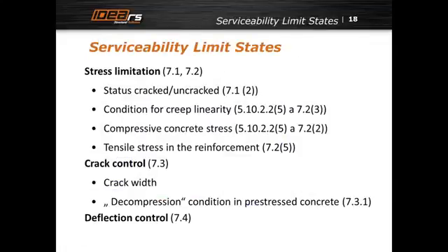Because I have limited time here, I wanted to only display all the serviceability limit states checks which we do with reference to the provisions of Eurocode. Maybe I could mention this status cracked and uncracked cross-section, which is required by Eurocode, which makes also this stress limitation. We can call it also allowable stresses or permissible stresses, as we know from other codes, which makes this analysis quite complicated, because it is in fact non-linear.